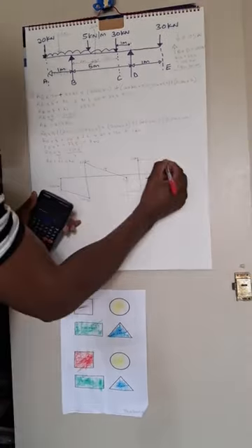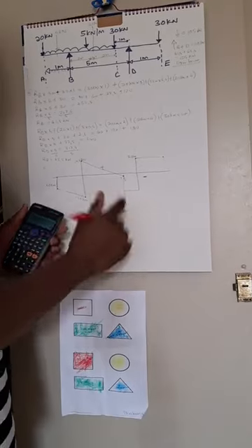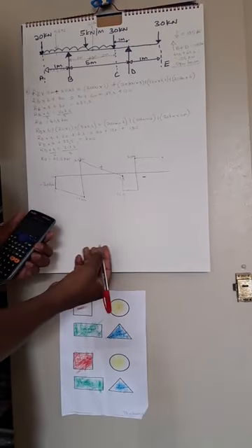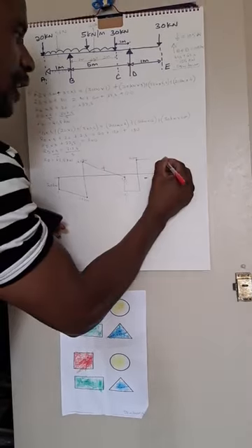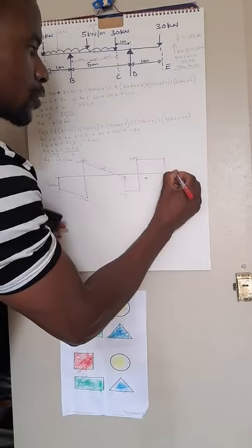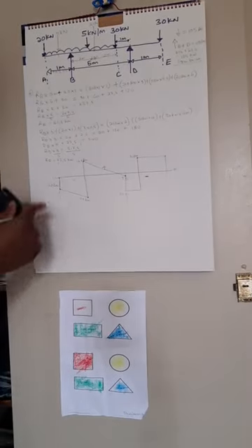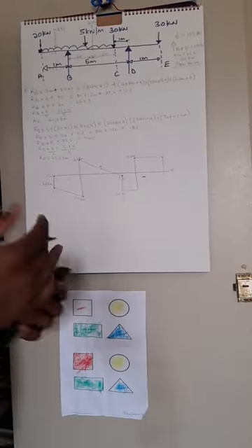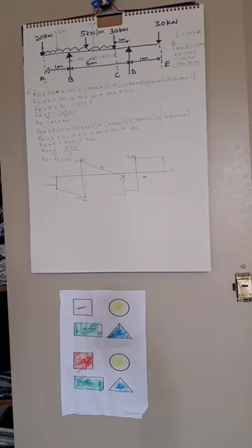So if you check at where we are at E. Now at E, where is the force going? The force is going downwards. So 30 minus 30, it gives us 0. So at this point, when you get a 0, that's where your shear force is supposed to be ending. I hope you are following.